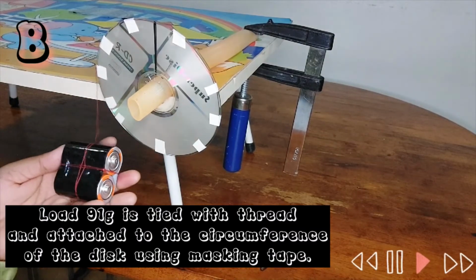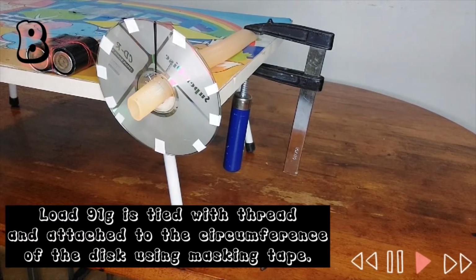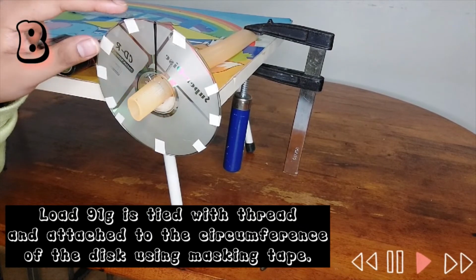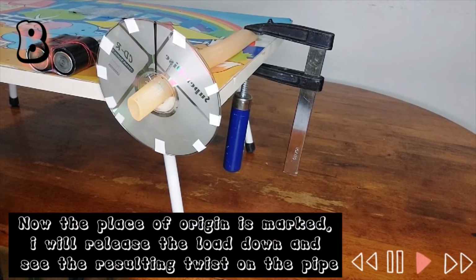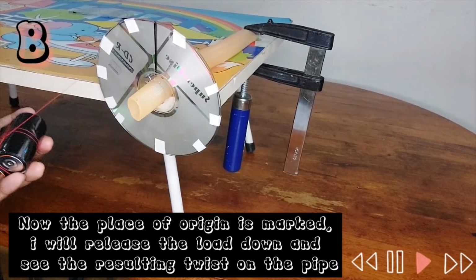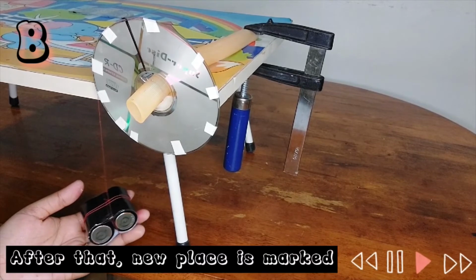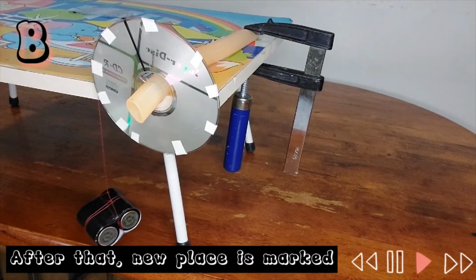Load 91 gram is tied with thread and attached to the circumference of the disc using masking tape. And then the end of the pipe is fit using a vise. Now the place of origin is marked. I will release the load down and see the resulting twist on the pipe. After that, I will mark the new place.